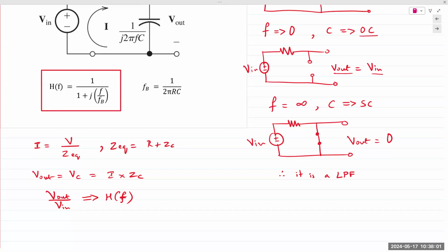You have a voltage supply, you're simply measuring the voltage at the output terminals. No current flowing, so the resistor is not doing anything. And then, in this case, because it's a short circuit, if you measure the voltage across a short circuit, output voltage is always going to be equal to 0. Because across a short circuit there's no difference in potential, output will always remain 0.